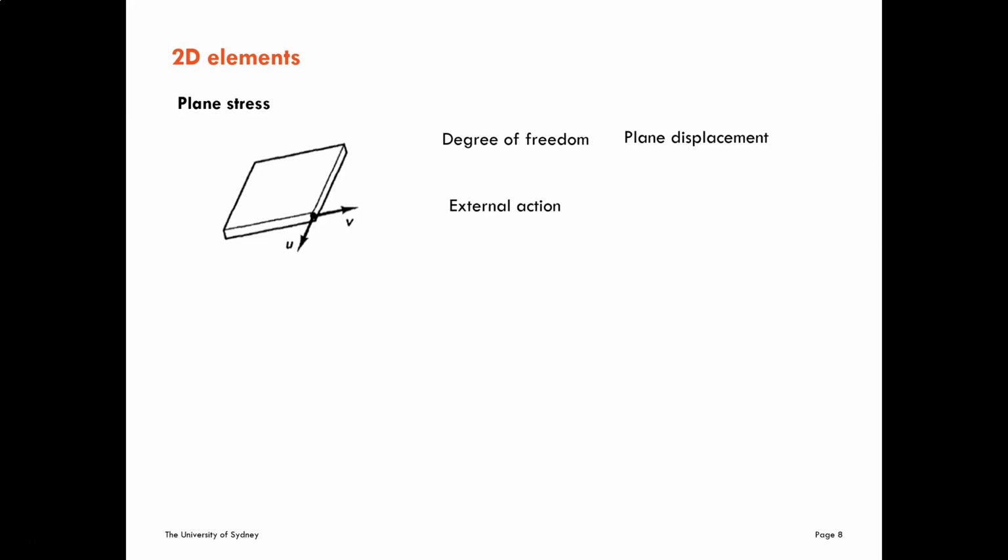Let's review the plane stress elements. We need these plane stress elements to construct our shell element. In this element, every point has 2 degrees of freedom that are represented by 2 displacements, u and v. So it's a plane displacement. So the actions in this plane stress are plane forces. So the forces only act on the plane.